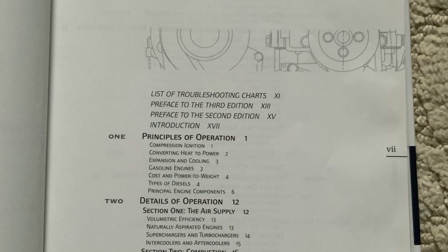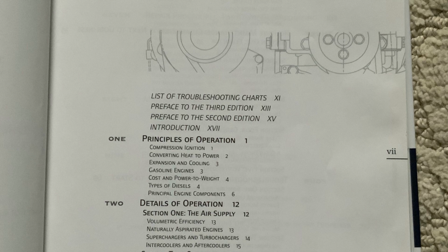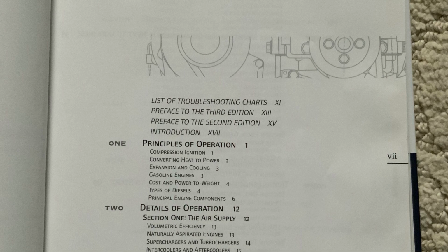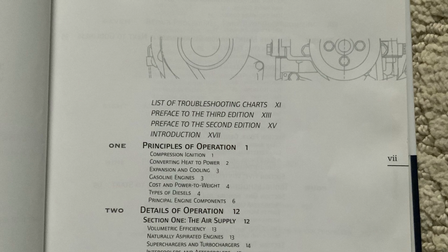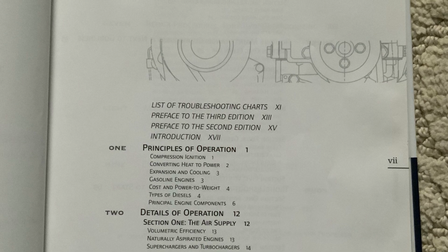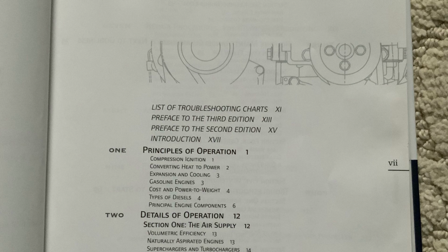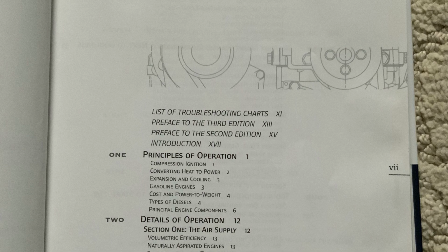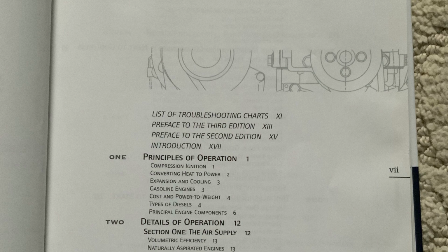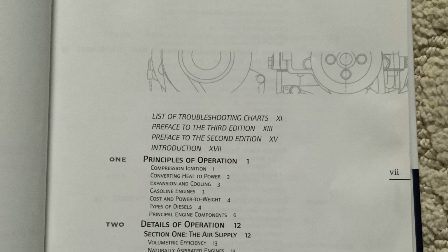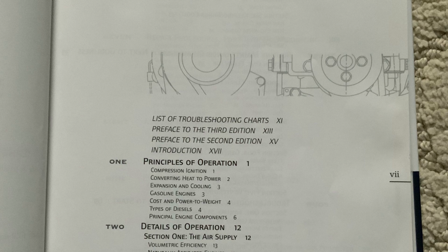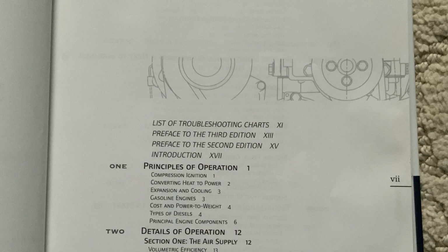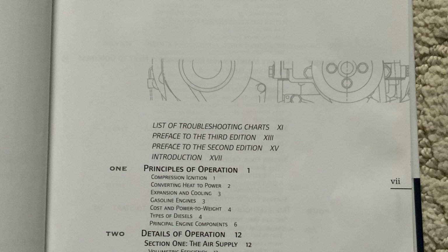See Figure 1-1. Diesel fuel ignites at around 750 degrees Fahrenheit or 399 degrees Celsius. Therefore, any fuel sprayed into a cylinder filled with air superheated to 1,000 degrees Fahrenheit is going to catch fire. This is exactly what happens. At a precisely controlled moment, fuel is ejected into the cylinder and immediately starts to burn. No other form of ignition is needed.